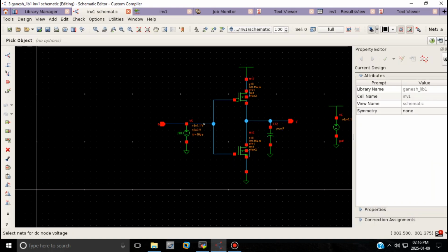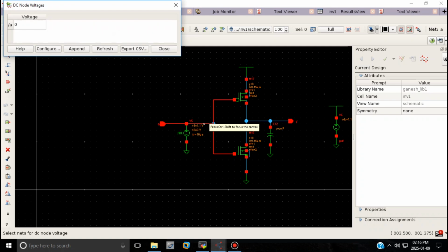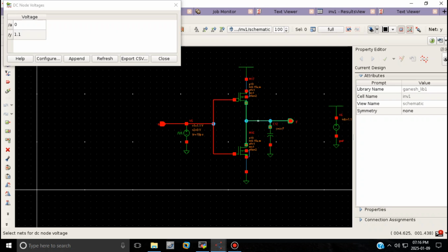So whatever the value across the node voltage we wanted to measure, we have to select the particular branch or node. So you can see the voltage across the particular node or the particular branch. Similarly, you have to select however many branches you want. This branch is given 0, then you will be getting logic 1. Logic 0 means we are getting logic 1, right? Exactly, inverting operation. The functionality, even you can check it like that. Instead of transient analysis, you can check the functionality of the circuit also with these notations.